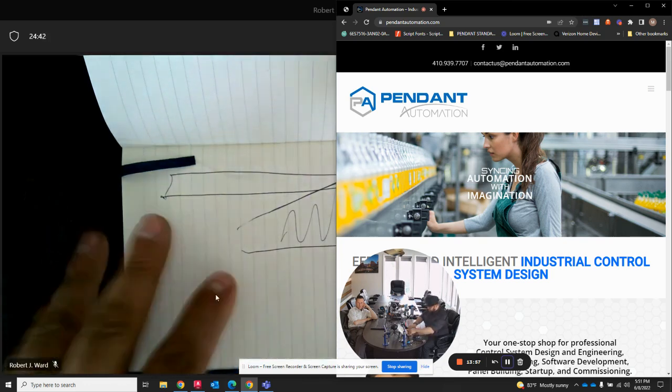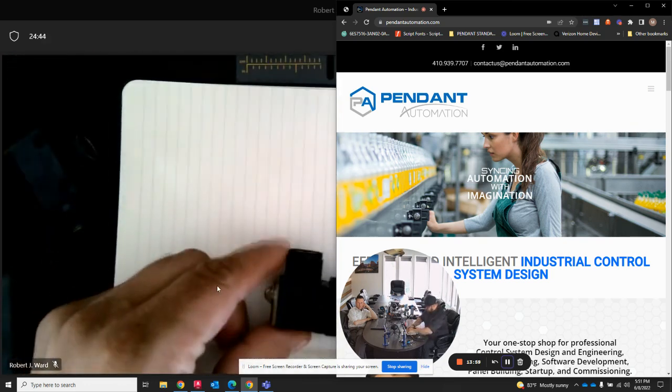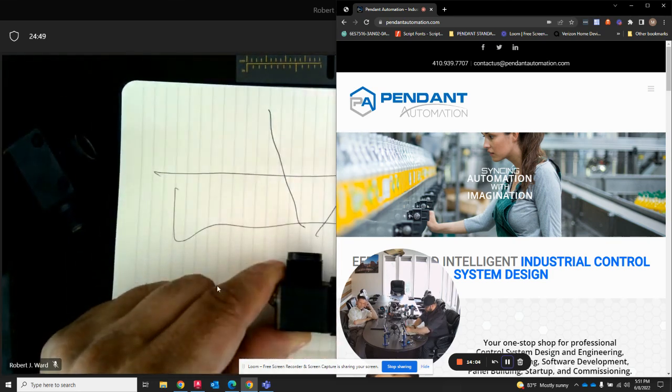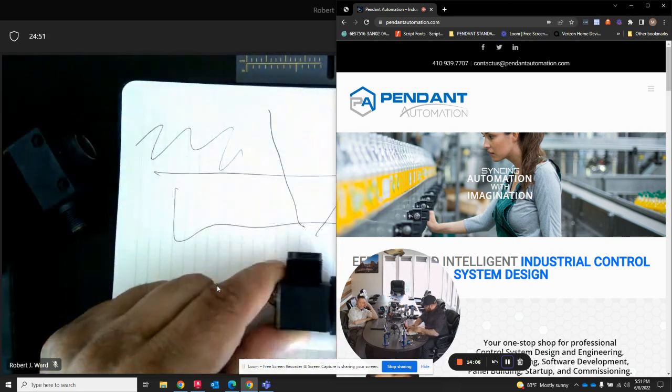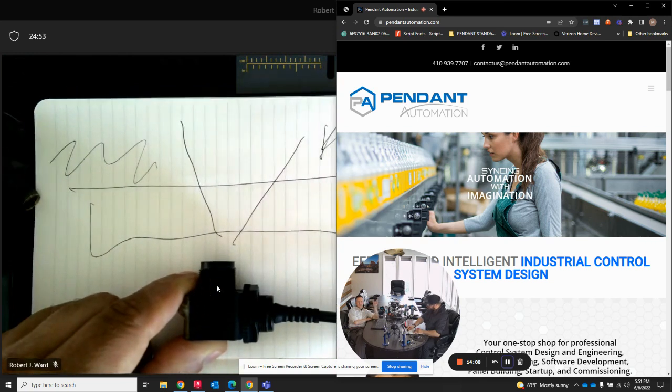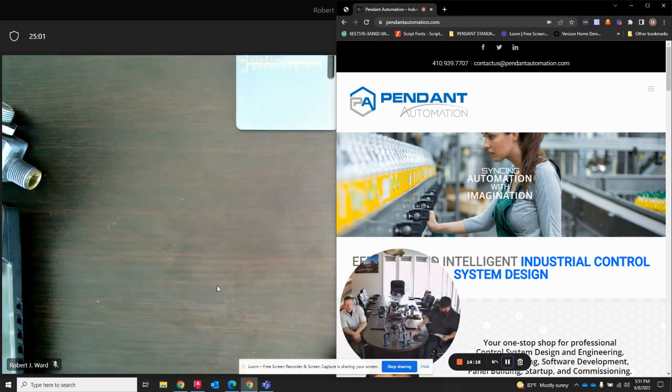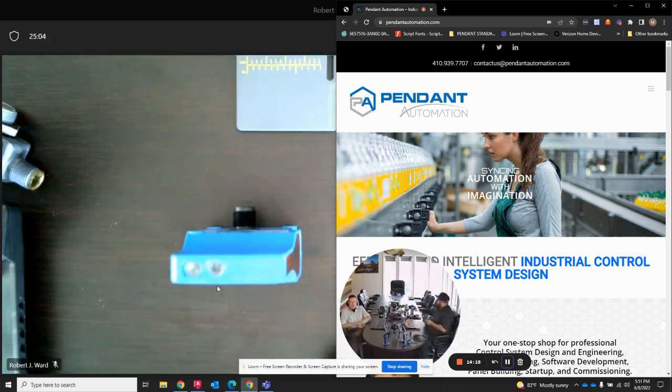Whereas if you were to mount just this sensor, and again it's conical, right? Exactly. You have a bunch of dead spots. So you went from 90% of the conveyor width being sensible, and now you only have about 2 inches. Absolutely. So on a 24-inch conveyor, you have almost nothing. And so if a box wasn't justified, you're going to miss it every time. Whereas this eye that we're showing now, if the box wasn't justified, you'd see it every time.